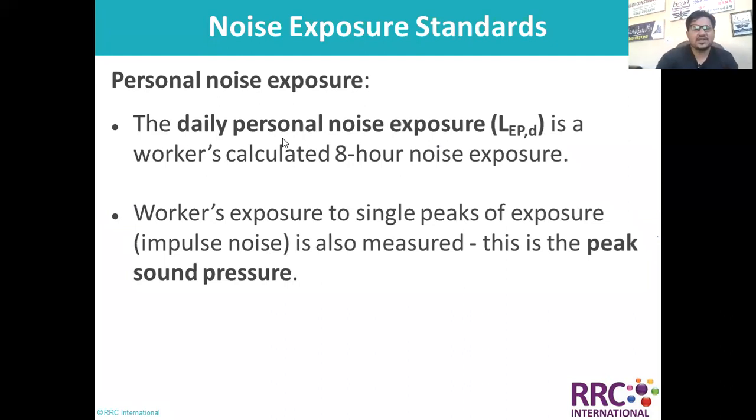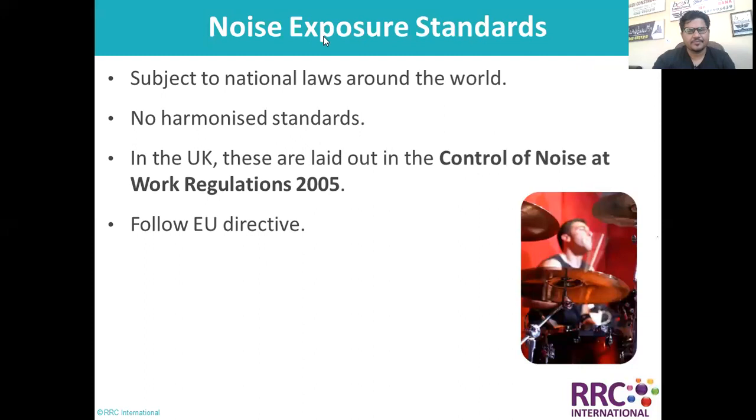We have to understand the personal noise exposure, like daily personal noise exposure. The worker's calculated 8 hours noise exposure, and the worker's exposure to single peaks of impulse noise is also measured. This is the peak sound pressure. So we can do some analysis. Yes, there are noise exposure standards subject to national laws also.